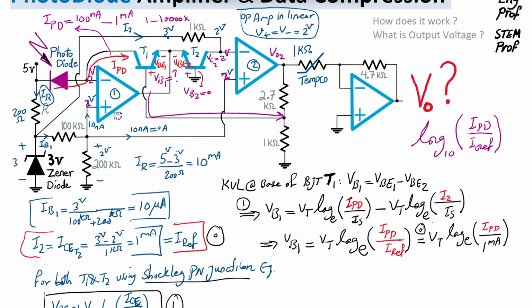Okay, so we got to the voltage of base 1, which is this node, at the middle of these two resistors, 1 kilo ohm and 2.7 kilo ohm resistors. By the way, for the sake of better design, it's recommended to use good resistors with 1% or less variability, which are decent resistors. It's not as if you're talking about very unique resistors. So I recommend using 1% or better, the less, the better.